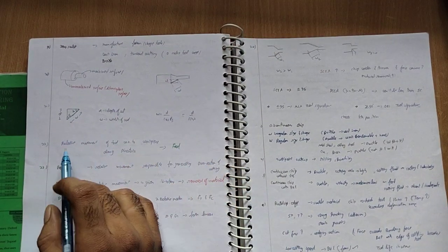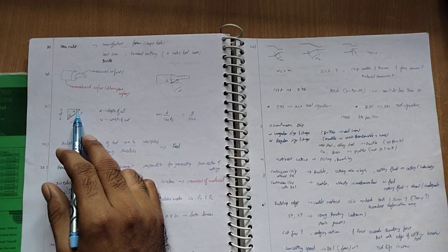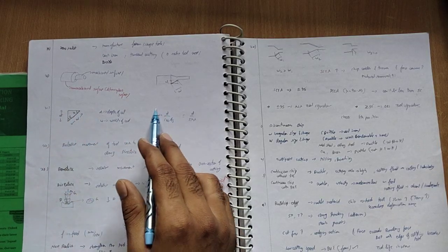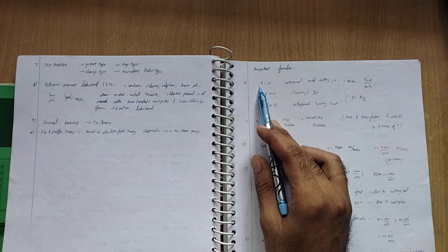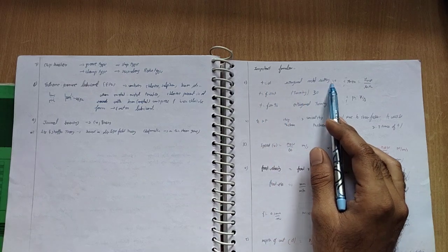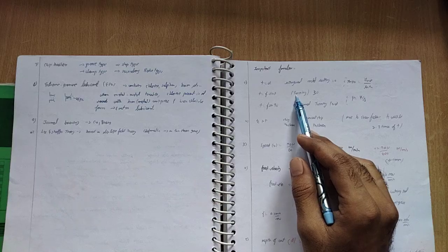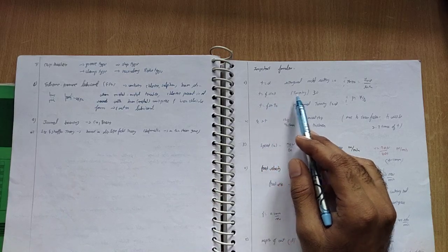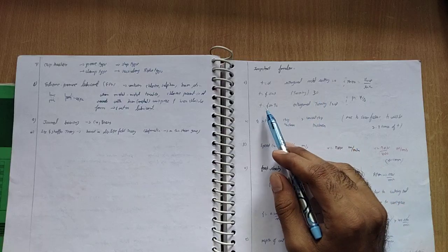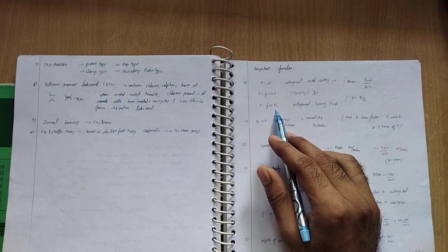Before that, you can see this one is depth and this one is width. This one is the cutting edge and this one is lambda. Based on this you can calculate. The important formula: t equal to d, thickness equal to depth of cut, for orthogonal metal cutting, 2 dimensional. For turning, t equal to f sine lambda, t equal to f sine of the principal angle. This is 3D turning, and orthogonal is only 2D, so t equal to f sine 90 degrees.